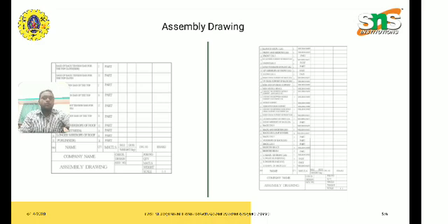The assembly drawing should also include words or symbols which define the technical requirements of the installation and use of components. We can see in contrast that there is no technical requirement listed in this figure, but detailed technical criteria have been listed in the other. Since the engineering drawing is a very flexible technical document, it is feasible that no words or symbols describing the technical requirements are added to the drawing when all comprehensive data including views, dimensions and title columns in the drawing can clearly describe the component specifications.